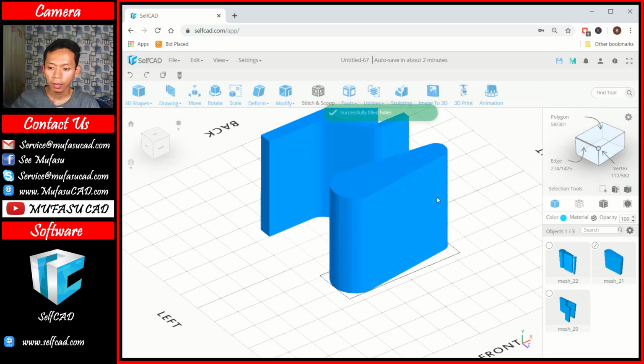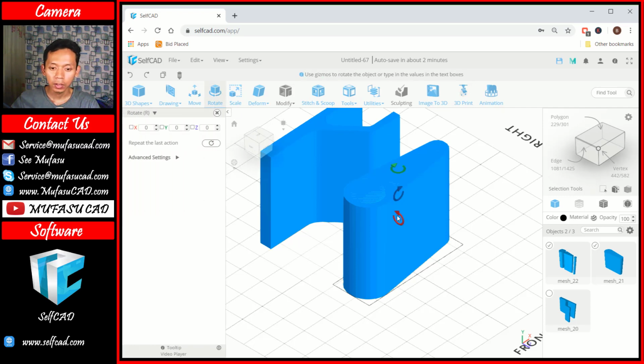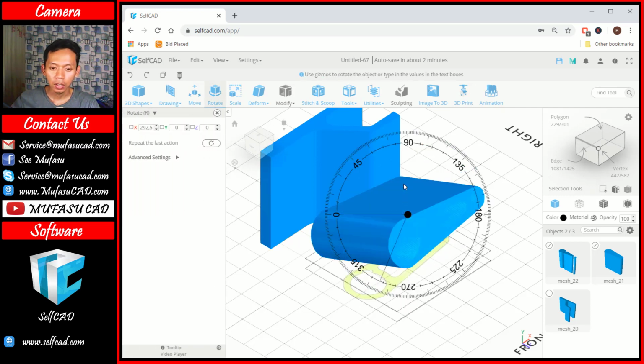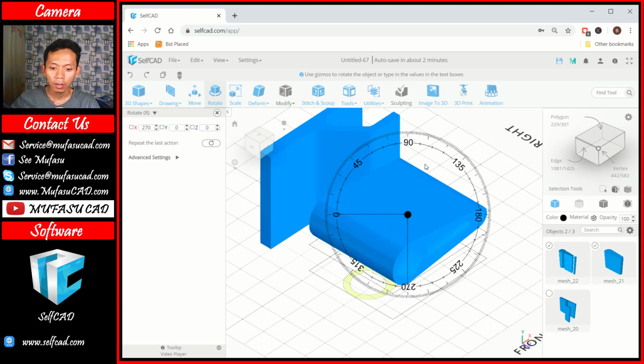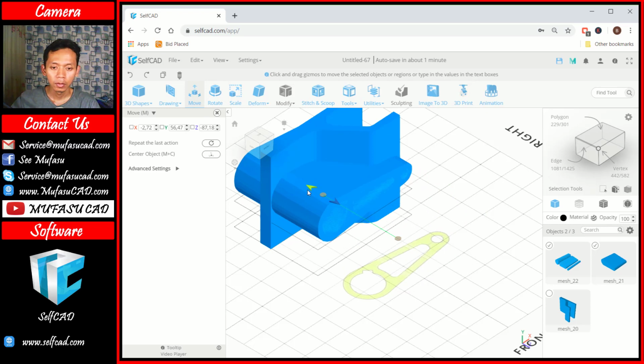Okay, now we can select these 2 objects, and I will use revolve tools. Okay, sorry, we use rotate tools, and I will rotate in red axis, okay, into 90 degree or 270 degree. We can use move tool to move these objects in blue axis into this point.